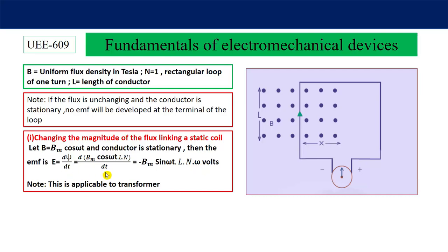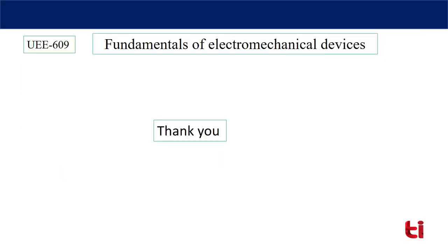Similarly, in case of motor and generator, we will see, as well as in case of induction machine, we can explain based on this structure. The only thing is that we have to develop this induced EMF. So today we have discussed just the basics of the transformer. To develop a varying magnetic field, an electromagnet is to be created, and that is obtained by applying a sinusoidal voltage across the primary winding of the transformer.